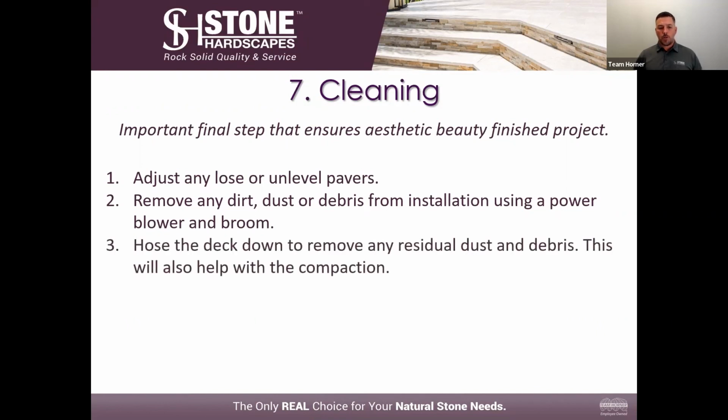Then you come along with a hose, and you can hose down the deck for any residual debris. This will also help with some compaction. If you have some loose pavers here or there, and you have to put a little bit of sand in between them to lock them in, hosing the deck down will allow that sand to really penetrate through those gaps and lock those pavers in.